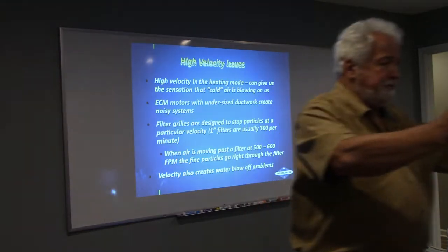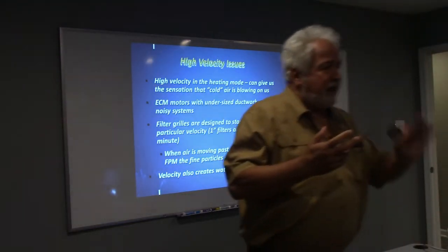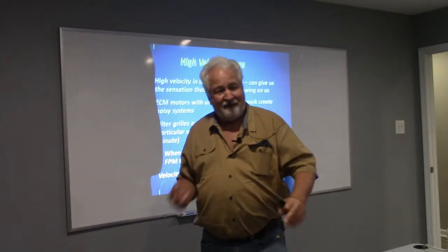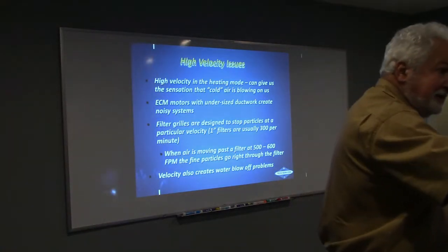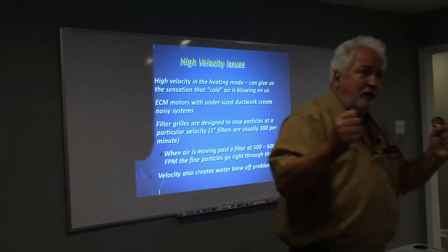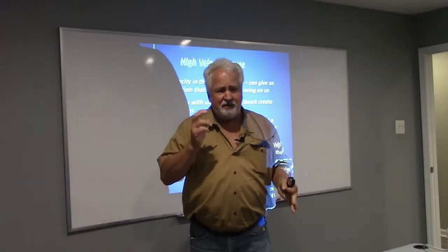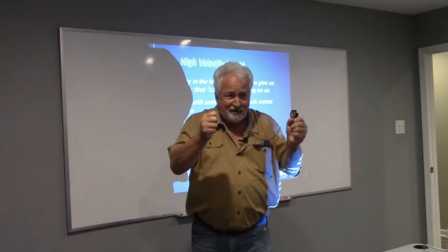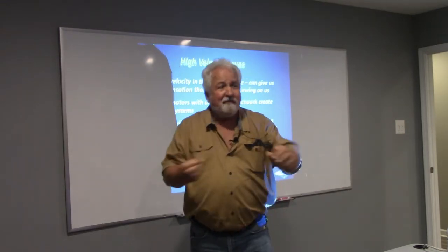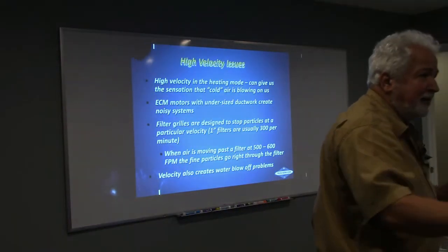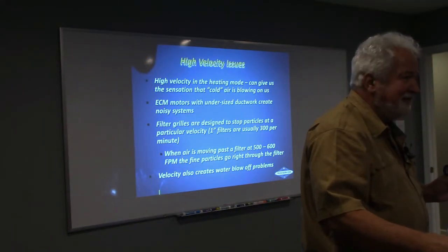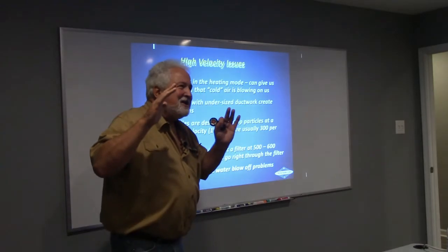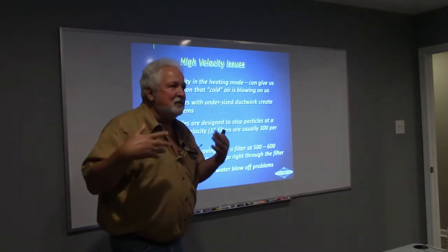So hold this filter up. You hold that filter, and that filter is designed to stop this egg at 300 feet per minute. Right? And if I throw it at 300 feet per minute, it does just fine, right? It catches it. But if you undersize it, what's happening to the speed now? What's happened to the speed if you undersize it a little bit? It's going to go faster. Going faster. So now it goes to 500 to 600 feet per minute. What happens now? Busts you in your face. The yolk's on you. Yeah, you see what we're talking about.